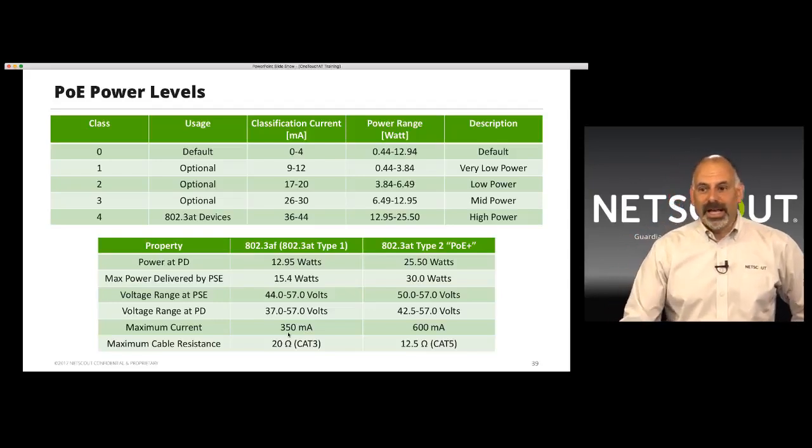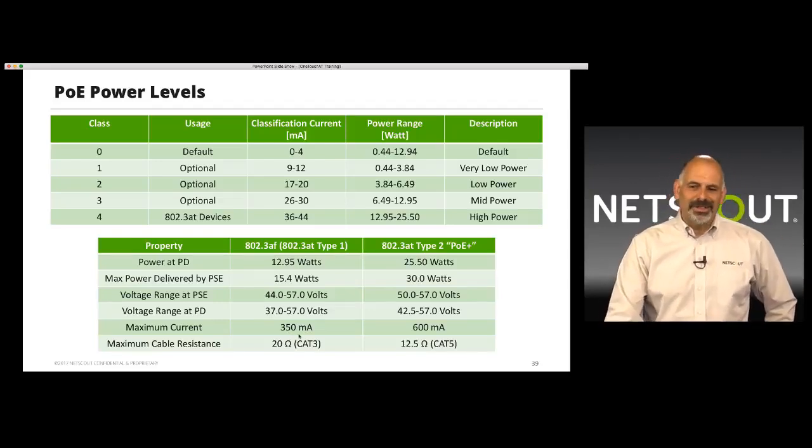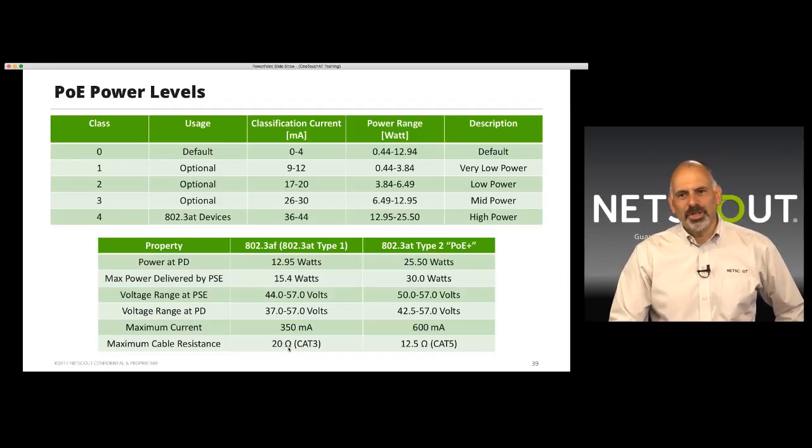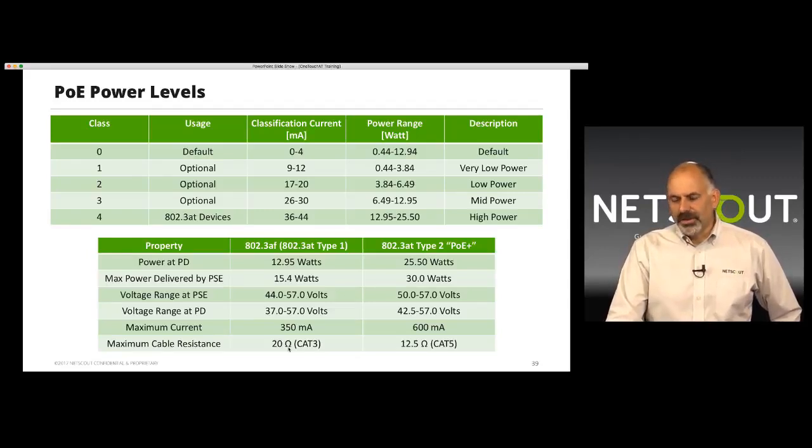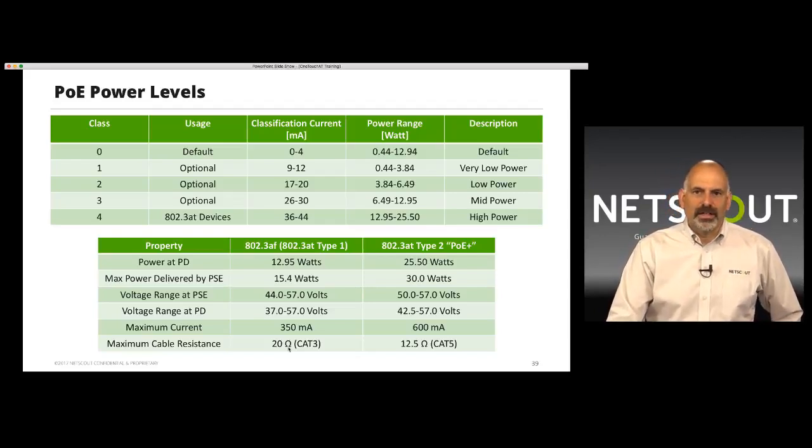A number of years ago, we ran into a situation where our Power over Ethernet was failing. After we did some testing with our cable test equipment, we found our return loss was failing, and it showed it was our cable. It turned out to be copper-clad aluminum wire.